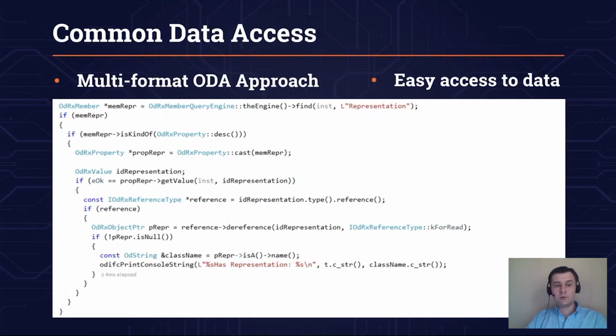And the fourth approach is the common data access. It's a multi-format ODA approach. You can also see a screenshot of some code example. It provides, I would say, easy access to data. So if you plan to work with multiple formats with ODA SDKs, it is reasonable to pay attention to this approach, because you will be able to access various data of various formats in a general manner.